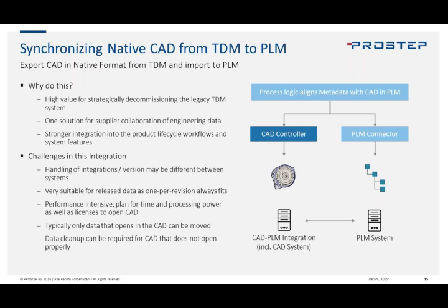Typically, you can only move data that opens in CAD, and if it doesn't open in CAD, you might need to do some cleanup. That doesn't mean it's always the case, but you might have things that were not updated for the latest change, so they're referencing old iterations or old revisions. Hopefully not, but it happens. It could be that things get out of date and don't synchronize properly, and you're probably going to have to handle those on a case-by-case basis.